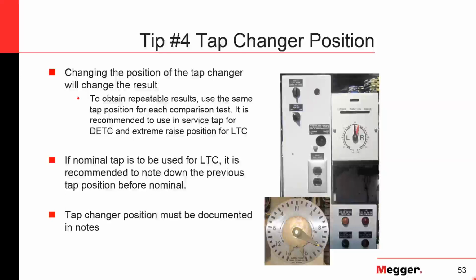But you need to correlate the test result, okay? If something flags up on your, say, open circuit test, you will try to validate that result with an excitation current test. People sometimes ask at a seminar, what do you think if I have 2 or 3 decibels difference now on my sweep frequency response, or it has shifted, I don't know, 10 hertz from the original benchmark signature that we got from this transformer.